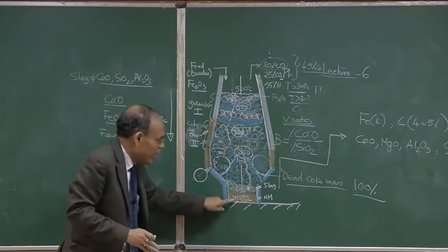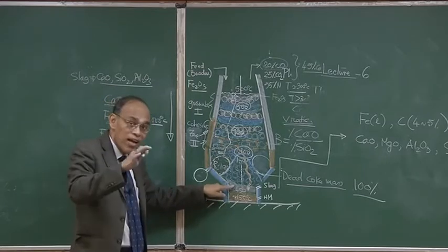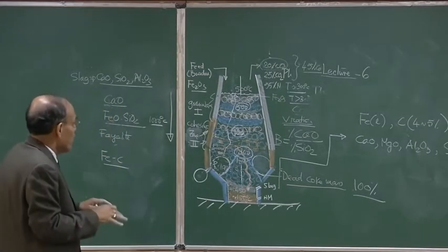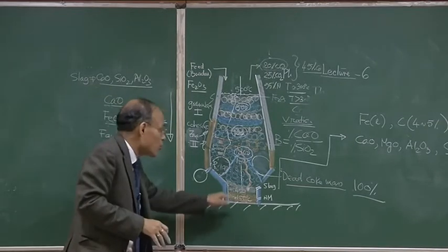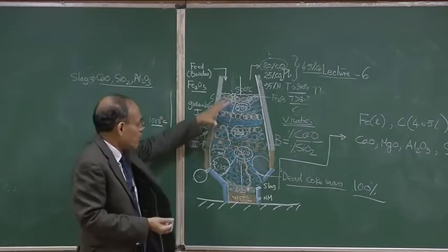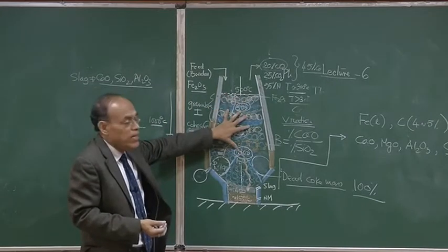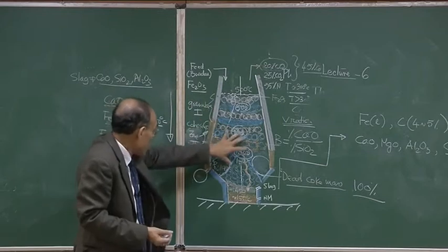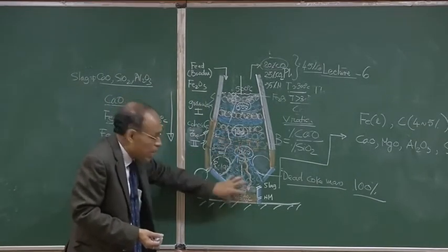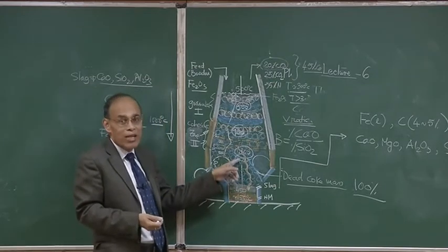And even when they accumulate here, the slag being lighter, oxides are lighter, there are reactions taking place, with the slag and the metal trying to arrive at chemical equilibrium with respect to each other, and there also the composition is changing. So, slag formation reactions, many slag reduction reactions, the limestone calcination reaction take place. Then carburization reactions take place, slag formation takes place, and then the slag metal reaction takes place. I am not trying to say that slag metal reaction will not take place here.